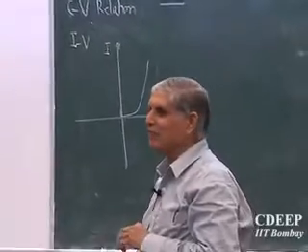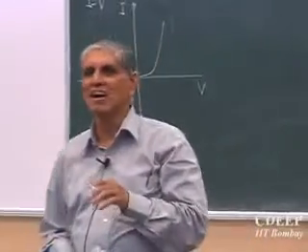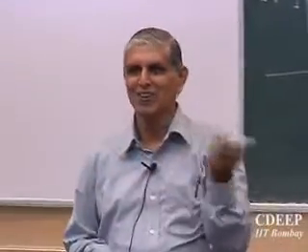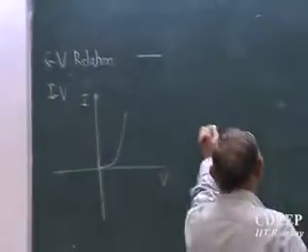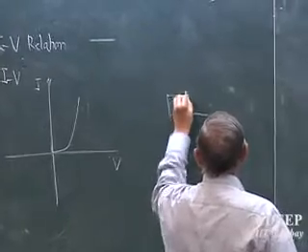I think you have preempted me. He is asking why I have always talked of reverse bias and never of forward bias. The problem is, as soon as I apply forward bias, something else will happen, and the capacitance effect will be much less. Or to say, the R shunting this C will not be as large. The equivalent of a diode, as I already said, is this capacitance shunted by this R.